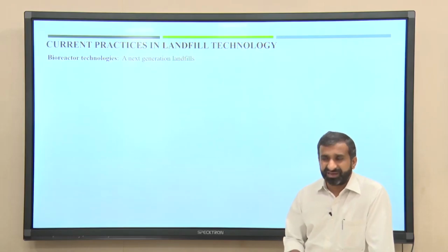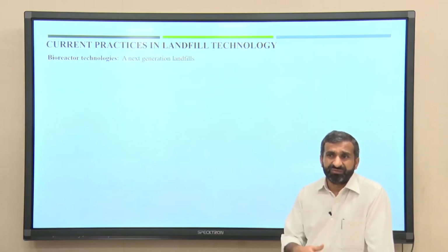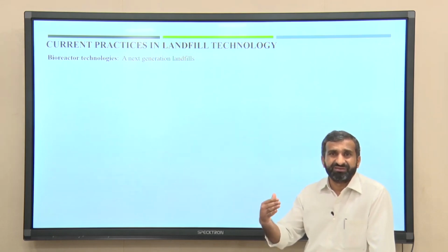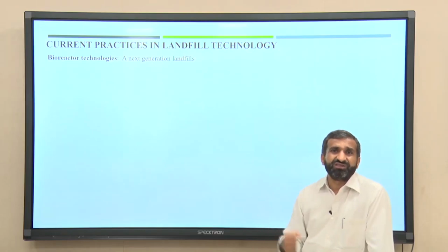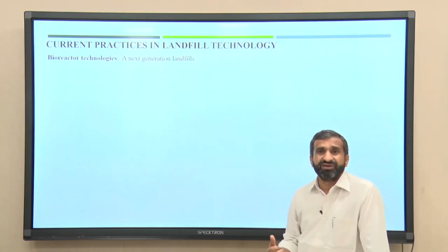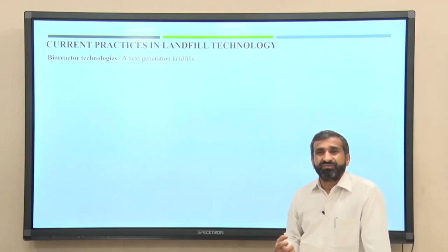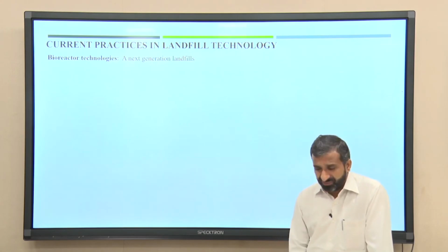But with leachate, as I was saying, initially the leachate won't be strong, and the BOD5 won't be that large, but after 4 or 5 years the quantity of leachate production is very large, and the quality is also very strong. So, I do not know how such biological treatment facilities will work.